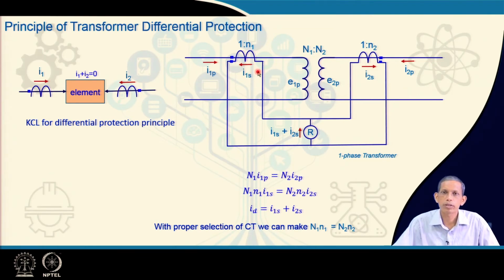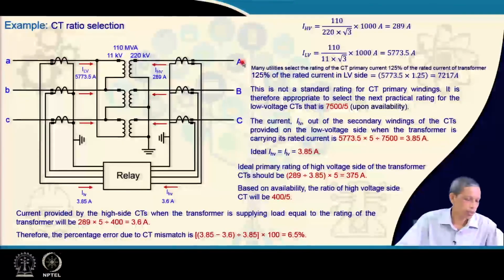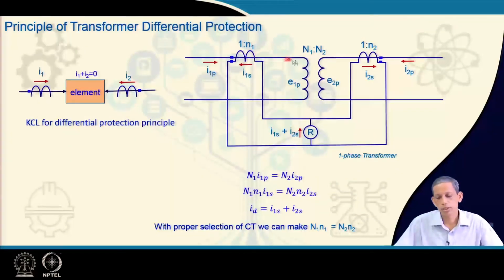Note, as we have already studied in current transformer case, the n1 becomes high, and the primary may usually be 1 turn or so. Similarly, the n2 will be high and the primary may be 1, but note here the corresponding main transformer has capital N1 to N2.